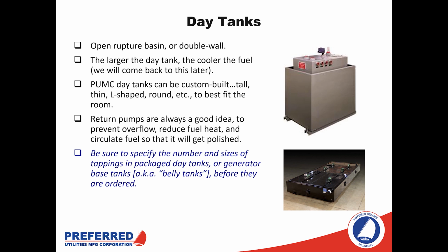Whether it's to remove fuel that is poor quality or to remove fuel that has been overheated by generator return, they are going to be critical for that as well as testing. So if we have this level sensor here and we're not burning enough fuel with periodic generator testing to allow the fuel level to come down and test the level sensors themselves, this return pump is going to allow us to do that manually on a periodic basis.